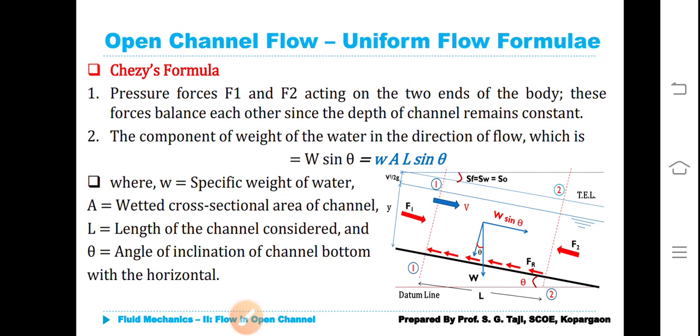Pressure forces, that is hydrostatic pressure forces F1 and F2 acting on the two ends of the body, balance each other since the depth of channel remains constant. The component of weight of the water in the direction of flow is W sin theta. Capital W is weight, theta is the slope of the bed with respect to the horizontal datum line.